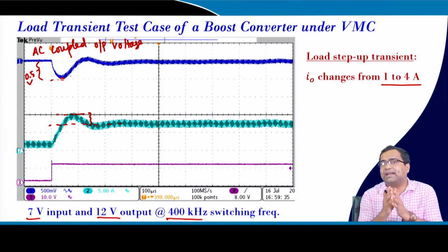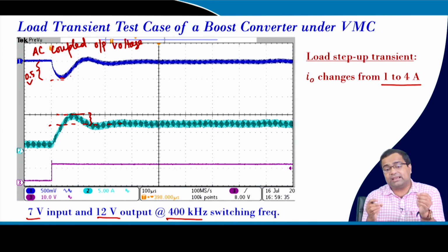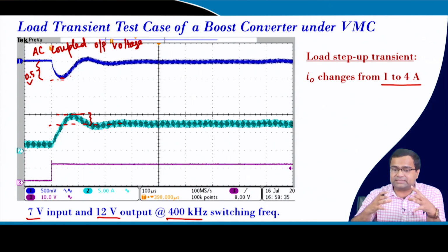And often you will find they may not match, or they may match closely, and this mismatch can have various reasons. Are you taking the right step to measure? If you introduce more parasitics into your converter or in the process of measurement, then the measured behavior is different from the actual converter behavior.